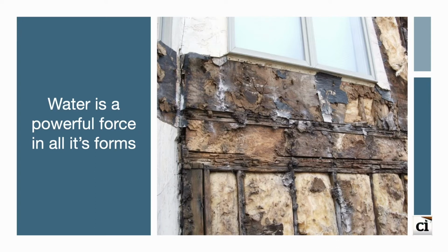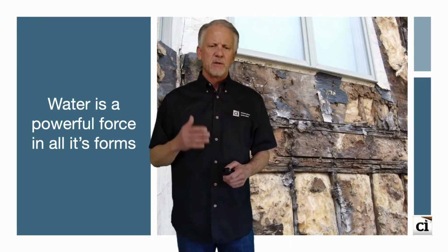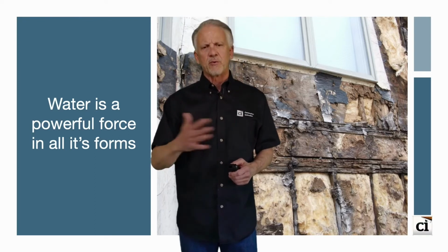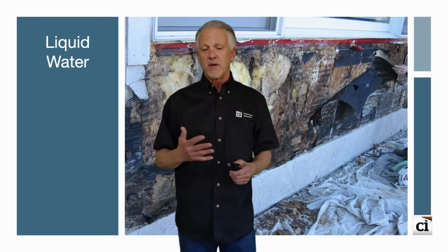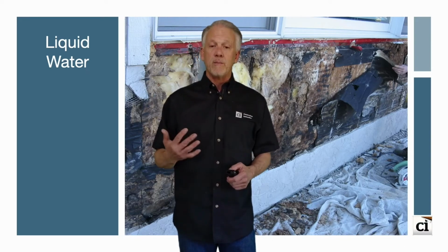These assemblies end up being stucco claddings that we're driving moisture through, being trapped at vapor retarders on the inside of walls and all kinds of complex issues. But thermal insulation and slower drying cycles really creates a challenge for our wood substrates that are all part of the way we build today.